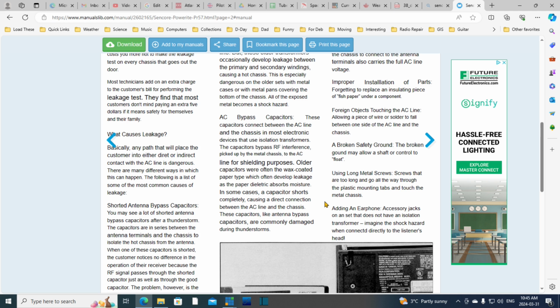So step potential is when you're standing outside the fence and your feet are apart about 1 meter. Now you're standing in such a way that when the wire falls on the tower and the disaster happens, a voltage exists between your feet in the ground. So that's called step potential, and that's also studied and controlled and engineered.